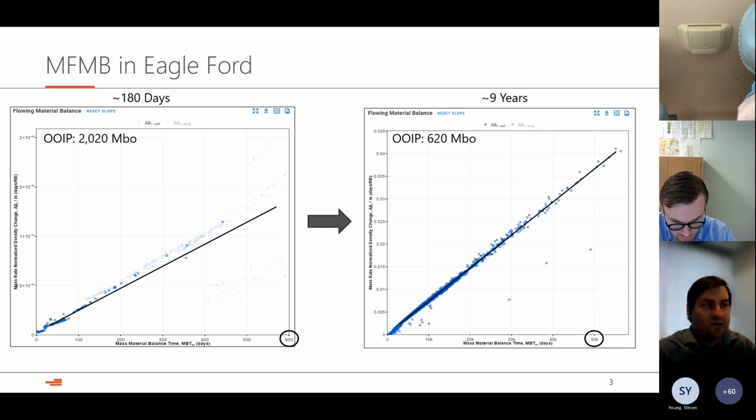So it takes us a while before we get through bubble point. And then we don't see significant rises, likely due to how tight our permeability is directly around our fractures. So we don't see huge pressure swings in those cells. We are benefited a little bit by that, so some of the analytical methods are okay here.